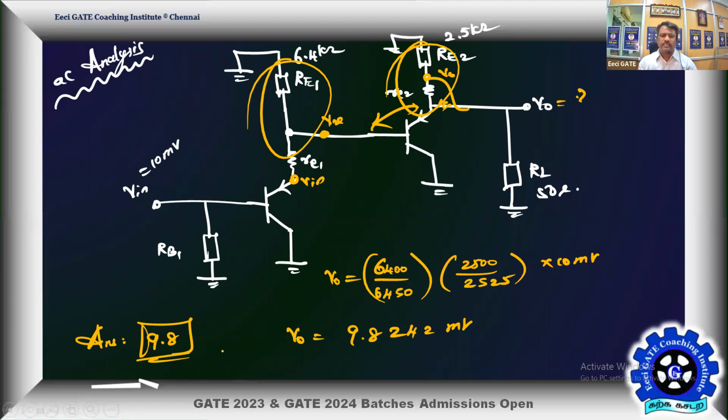We have to work carefully with the small signal equivalents of transistors Q1 and Q2. It's the same as how you work with NPN, so the habit of working with PNP will help you there. Keep the emitter at the top itself, so that you can verify whenever required whether the AC equivalent we have determined is correct. It's an easy verification as well, two potential divisions. Bring the two potential dividing factors into play. This is one, this is another. Multiply with the input, and that's your result. So it seems to be a perfect answer.